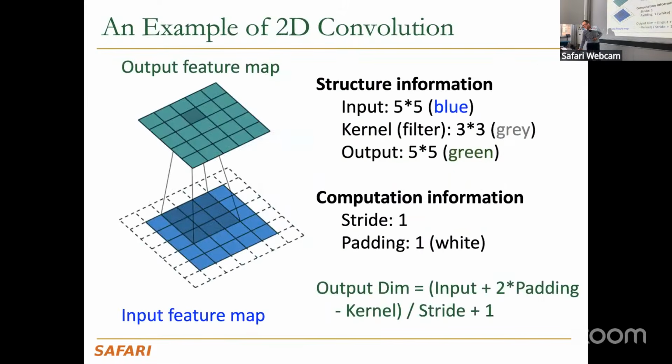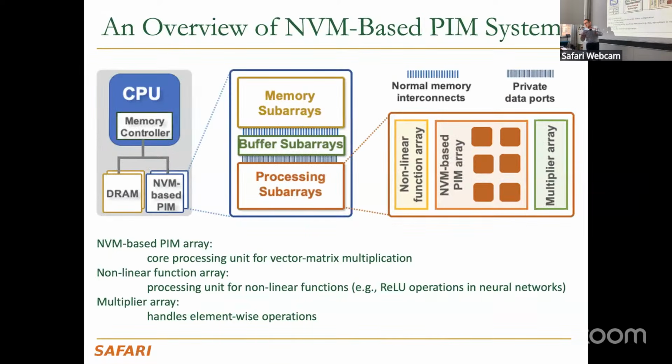With just multiplication, with Kirchhoff's laws, you can only do multiplication, unless someone comes up with a way of abusing more of this. Let's see. So for other things, you need to actually add more memory, add more computation units inside the memory to do other functions. So in machine learning, there's certainly multiplication, but multiplication is not the only thing. You have some nonlinear operations, for example. For those, if you want to do them on the memory side, you need to add near memory logic. So people usually combine processing using memory and processing near memory when they do this sort of non-volatile memory-based PIM.